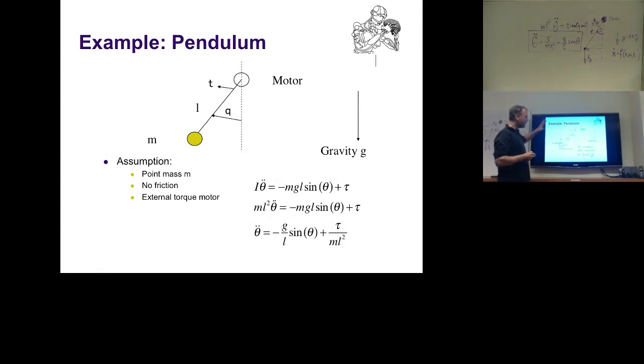Cool. So we derived, just in a very ad hoc, intuitive way, a model of a system. We haven't done any observation equations in this particular case. Observation equation would, for instance, just be that, can we write this down? If you can only observe here with a position sensor the position theta of the pendulum, well, then you could just write y equals the complete state of the system is obviously theta and theta dot. This is the complete state.